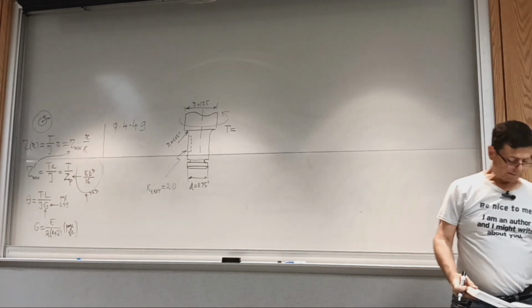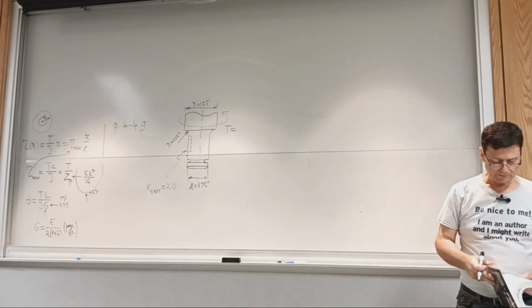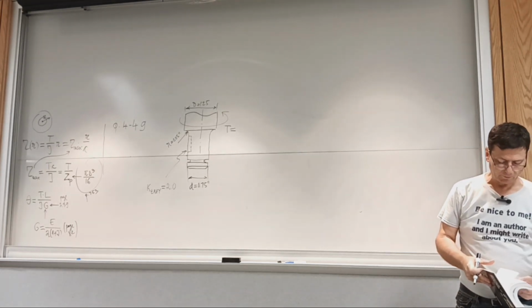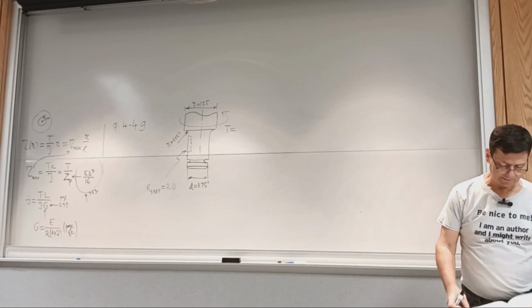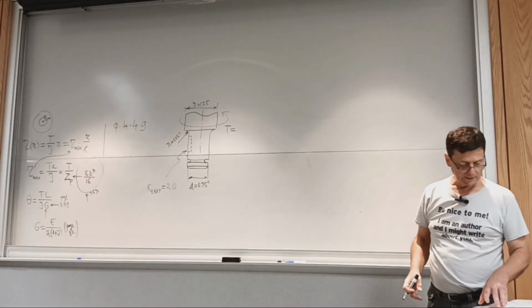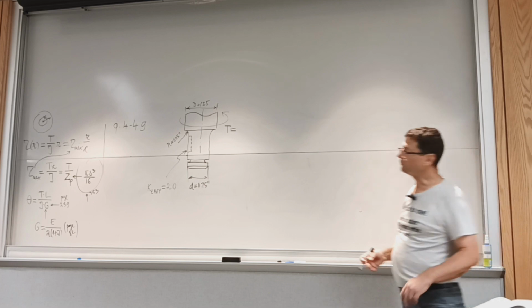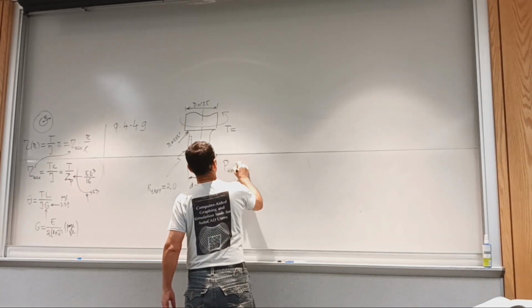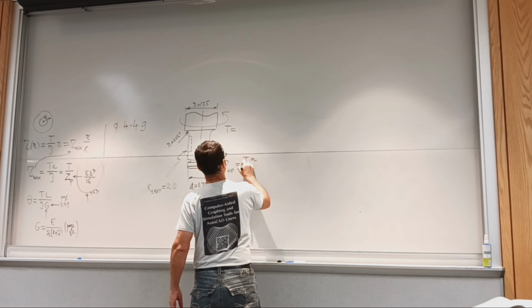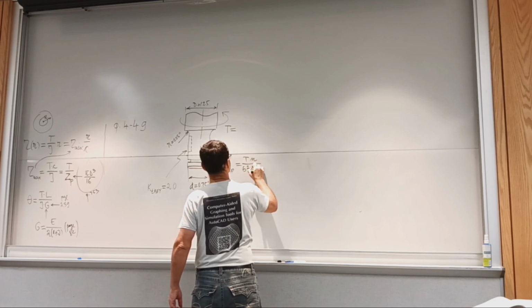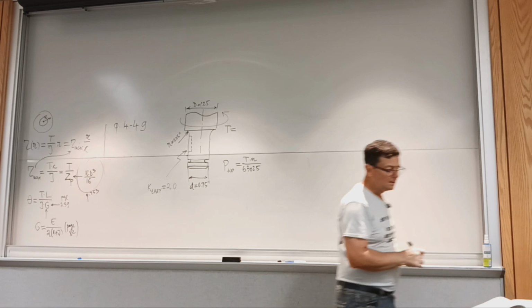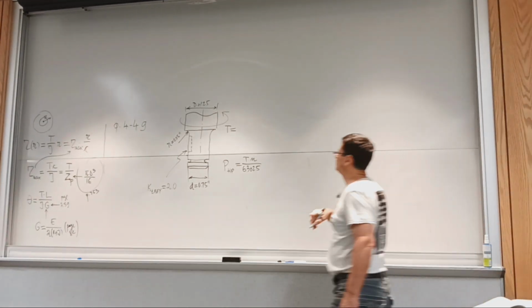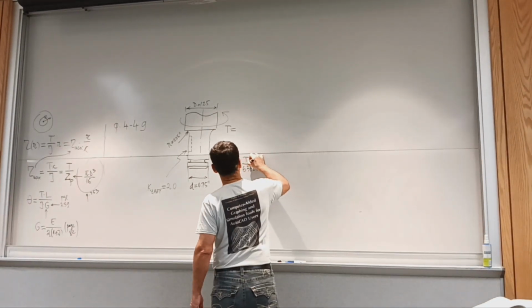So to calculate the torque, we are using the power equation. I have it added, the advantage of using the paper book, but it's in the text. So power in horsepower, we have that equation. It's torque times RPM over 63,025. Is it? 63,025.